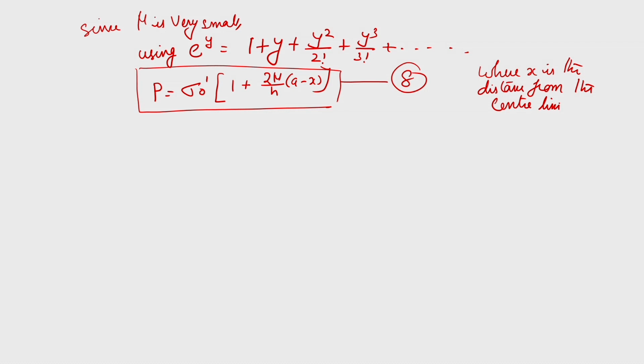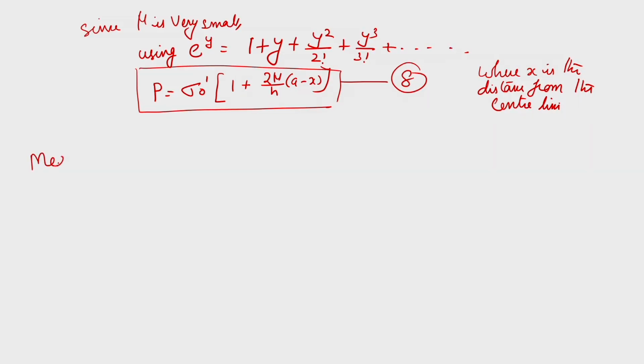Now, for analysis purpose, it becomes much easier. So, we can also find out what is the pressure distribution, the stress distribution at the die from the center line. That variation we are getting, but for calculation purpose, when we wanted to find out the forging load, a simple method is by calculating the mean forging pressure and multiplying with this. Otherwise, you will have to keep on integrating from the center to the surface. But if you are assuming the mean forging pressure, this can be calculated if you are considering only one side,